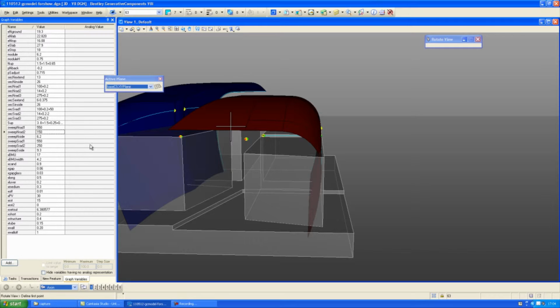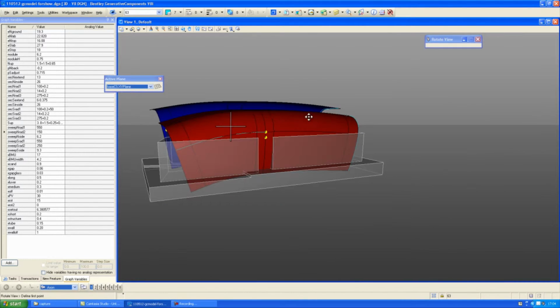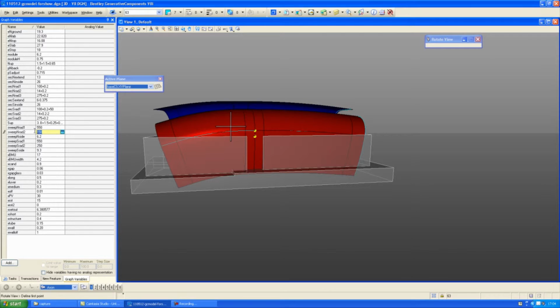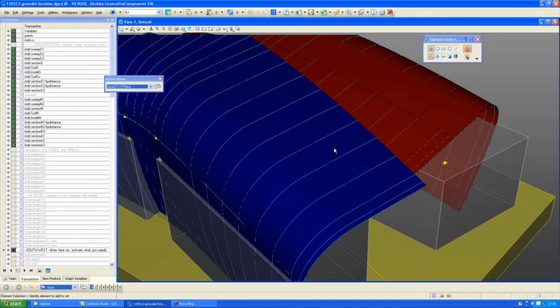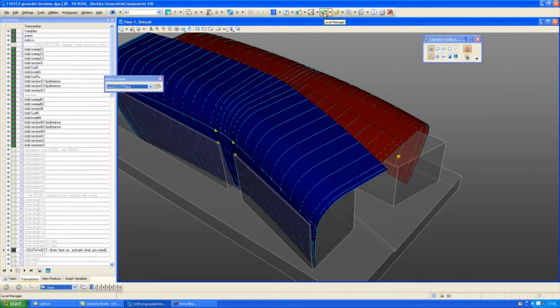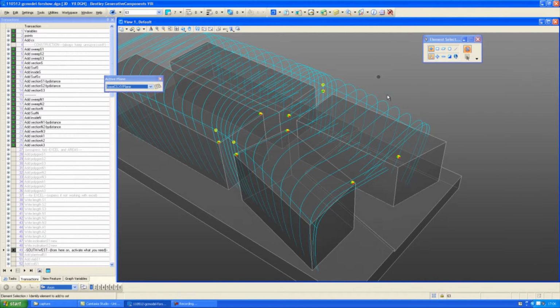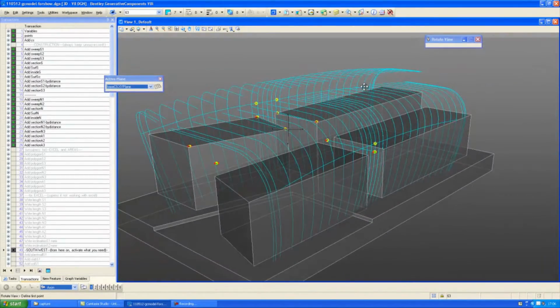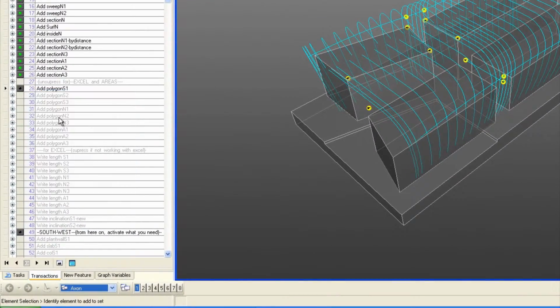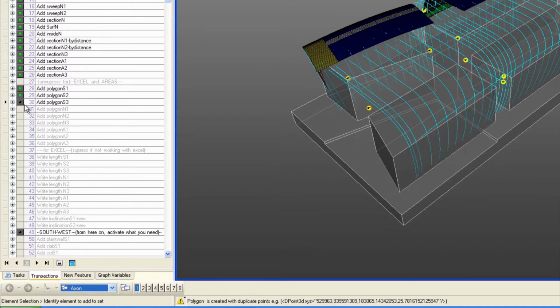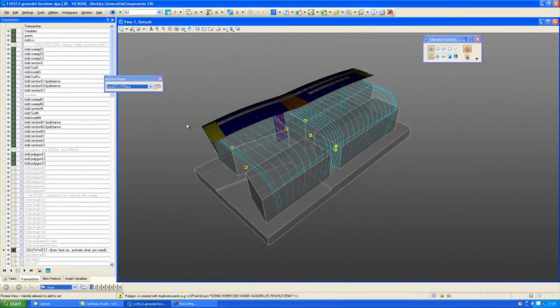For example, in this case, we'll be having tapered end profiles for stainless steel structural members at the edge of the roof. The angle of these tapered end profiles is going to be parametric. We divide the surface by intersecting the planes based on the structural grid, and these intersection lines act as center lines for our linear structural members. We'll be having various types of roof panels like skylights, photovoltaic panels and solid panels, etc.